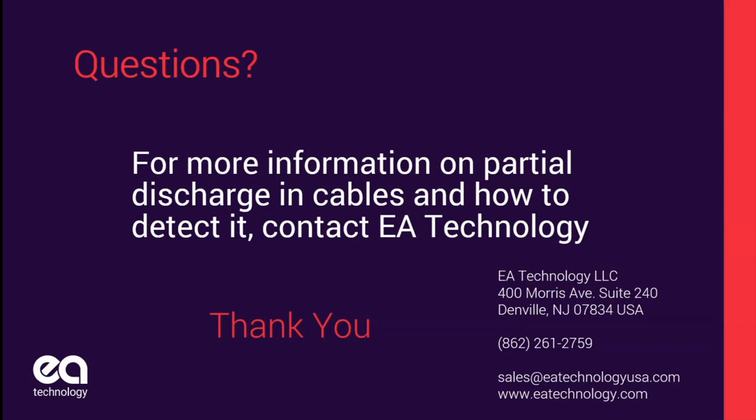Are Rogowski coils effective for measurement? We have not used Rogowski coils, and I don't know their frequency range. We're looking up in the 20, 30, 40 megahertz range. I don't know that Rogowski coils go that high. I'm not an expert on Rogowski coils, but I think they're more of an under 1 megahertz sort of device.